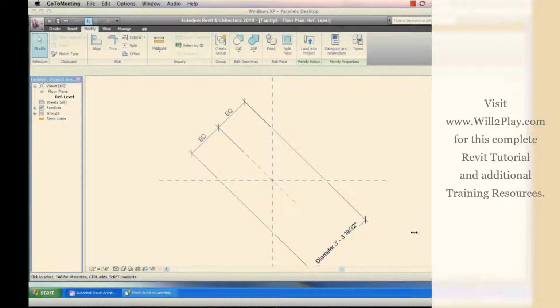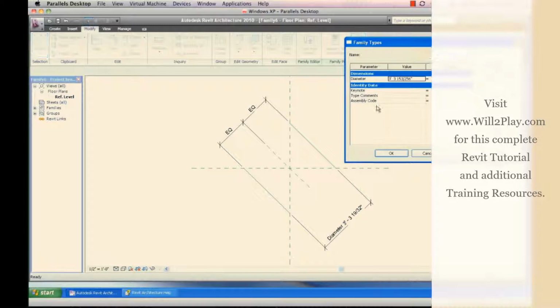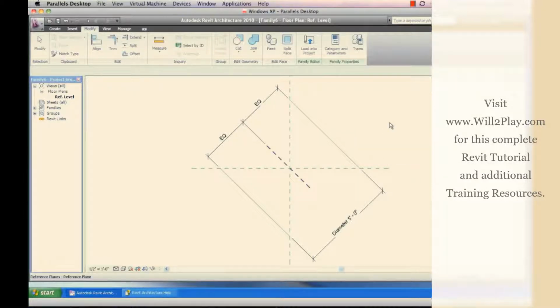All right, now we want to flex it, see if this works. I hope it does, because I haven't done this in quite some time. There we go. All right, so already we're starting to see there might be some things that reference lines aren't quite good at. One, equalizing dimensions. So this is why you flex. We got a reference plane as our reference point to anchor everything in, and we pinned it.